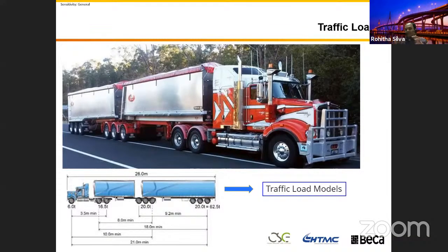That's where we use the influence line. When you design normal structures, for example a simply supported beam with a UDL, the maximum bending is WL squared by 8. But if you send a truck, a moving load, along that same beam, you can see your WL squared by 8 varies.